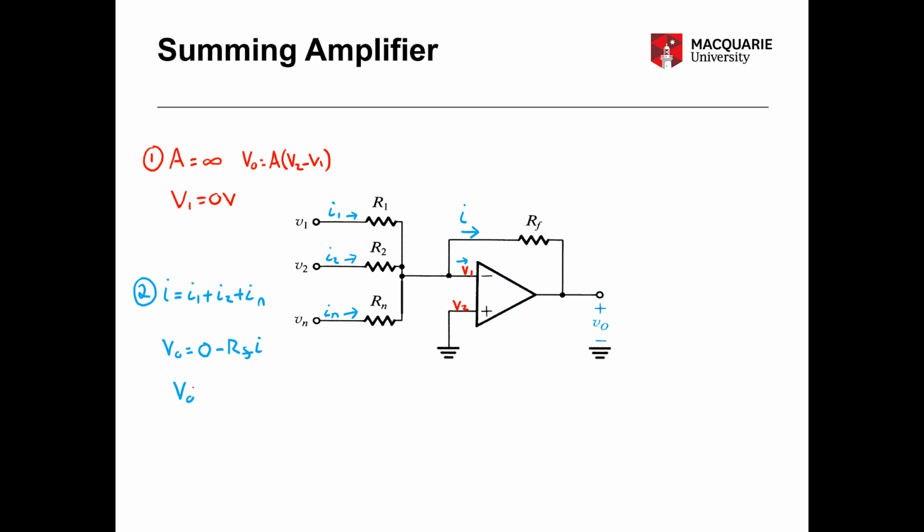So therefore Vout really just equals minus RF I. So to work out the value of the current going through the feedback resistor RF, so to work out this I, we can apply superposition. And that's because our circuit's made up of just linear components, all of these different resistors. And whilst we do have a non-linear component in the op-amp here, we're treating it under the ideal op-amp assumptions, and therefore using its kind of equivalent circuit and maintaining linearity within our circuit.